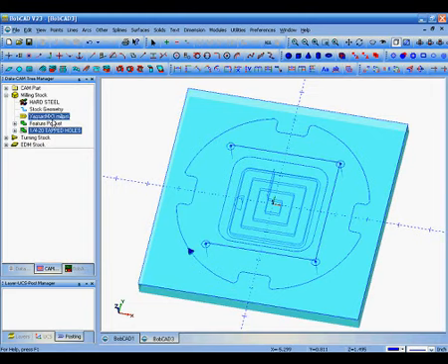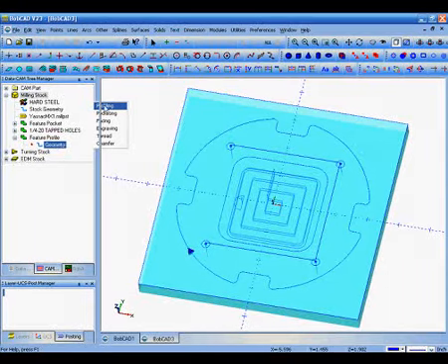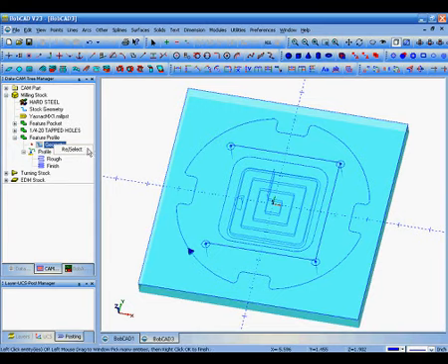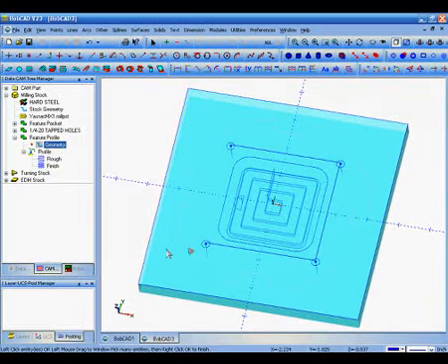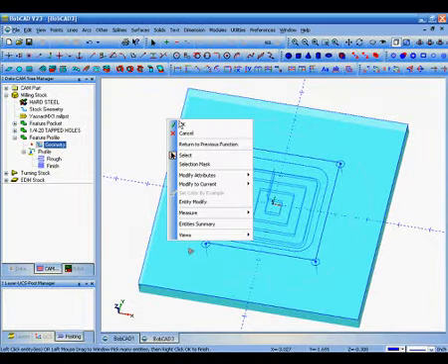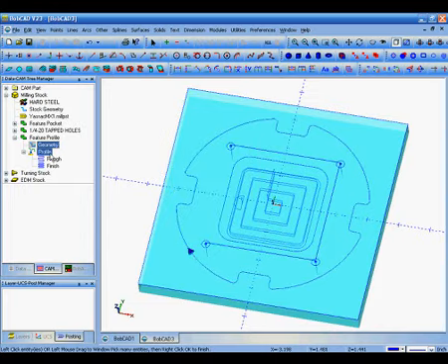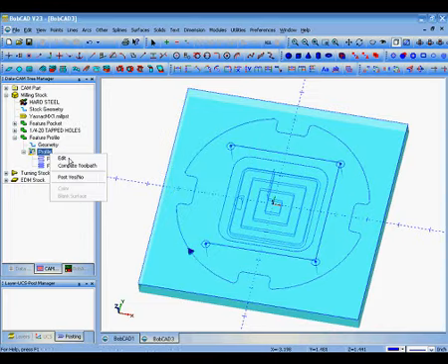Now we're going to add the profile cut. So we'll right-click Milling Stock, Mill to Axis, and then go to Profiling. Again, right-click Geometry, this time below Feature Profile, go to Select, pick the contour that we had made, then right-click and left-click OK to confirm our selection. Now we'll right-click Profile and go to Edit.